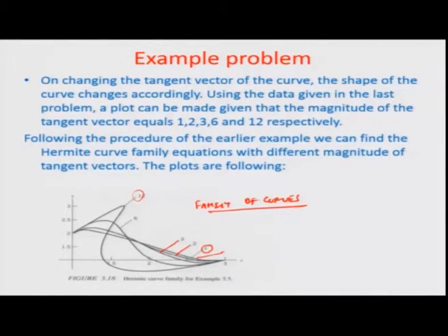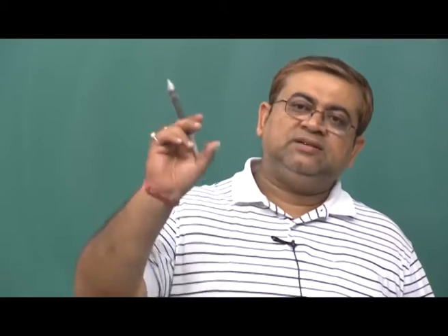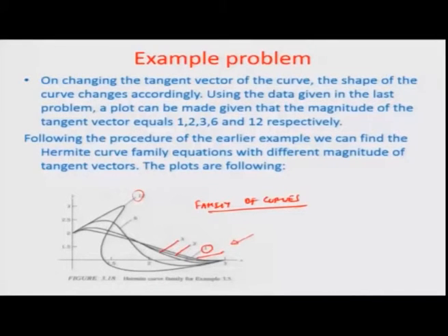So, this is the beauty about this process, that you can divide a surface into small curves, and complex organic forms which need to be mapped into a computer in terms of some data and some data management can be very easily stored on the basis of such synthetic curves. So, this is one very key example of how you can do contour mapping through curve fitting exercise using the simplest Hermitian cubic fit polynomial.